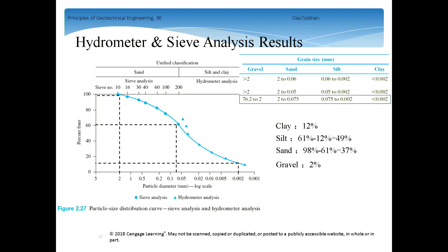Yes, maybe if you sieve for half an hour or 1 or 2 hours, the percentage may change, but not too much. 15 minutes is enough. Maybe particles will break, but the sieve is not strong enough to break a particle. It's just strong enough to let those particles pass those openings. But as long as it can break, it is two particles, not one particle.